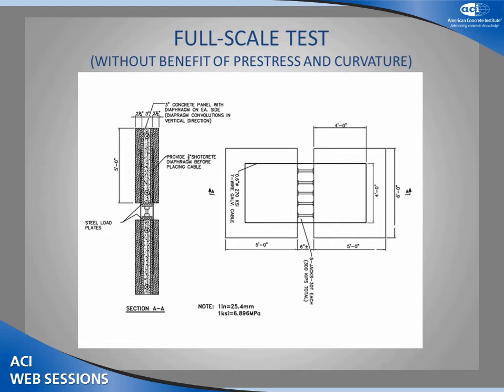What we did was, we held the diaphragm; there are two sheets of diaphragm on either side of the concrete. We poured concrete inside of the diaphragm, and once it hardened, we put base cable on the outside, and then we applied shotcrete. And that was our system. Now keep in mind, this system gives us a lower bound solution.